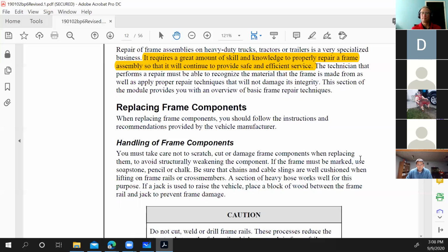That's a big job. I've plated 2 complete gravel trucks from front to back with one piece of channel. So it's very similar to that. We didn't replace the frame rail. All we did is disconnect everything from the frame, and then essentially from the back to the front, you slide in new lengths of frame, the entire length. And it went from an inside C channel to an outside as well.